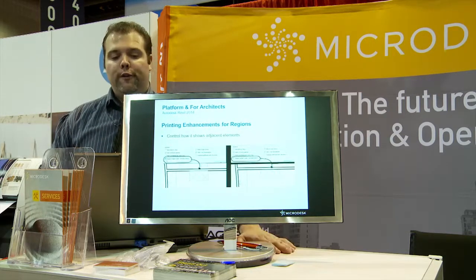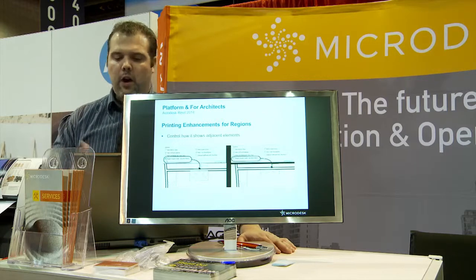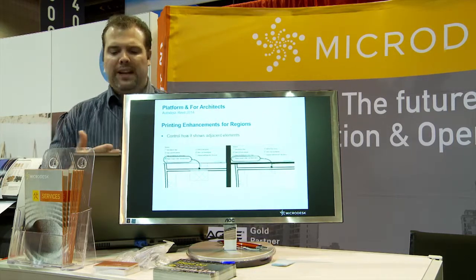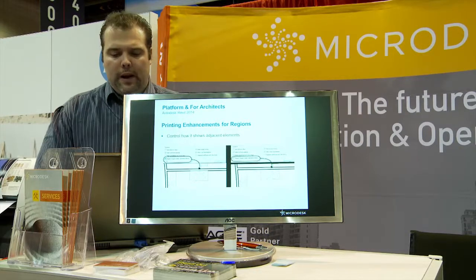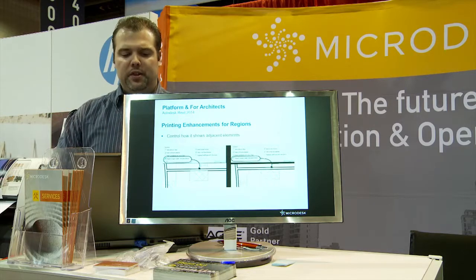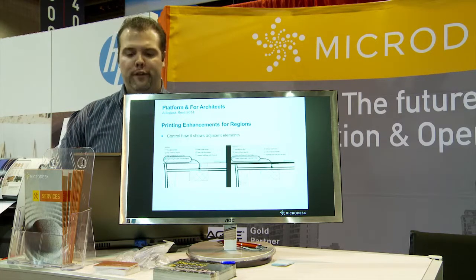And now, talking about annotation and how it looks in terms of graphics, one thing that was commonly a problem was anything hatched in Revit: when you had overlapping lines, you had a weird representation. Now that's something you can check on and off and really tackle.